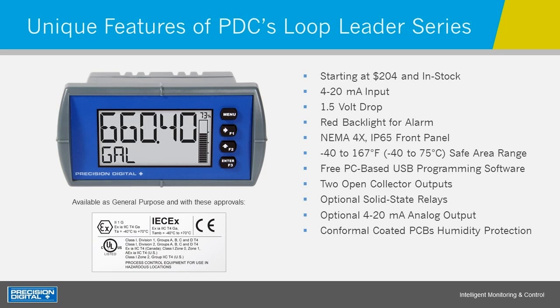With the amount of power these are using, small amounts of corrosion or contamination on the printed circuit boards can bring in humidity, can change really small resistances, and that can have a big impact on the display starting to jump or become inaccurate or lose its ability to turn on at certain milliamp values, etc. Because again, we're talking really low power inside of the unit. The power draw is very small. So to prevent any of those issues, Precision Digital goes the extra step of sealing all of our printed circuit boards to prevent that from becoming a problem.